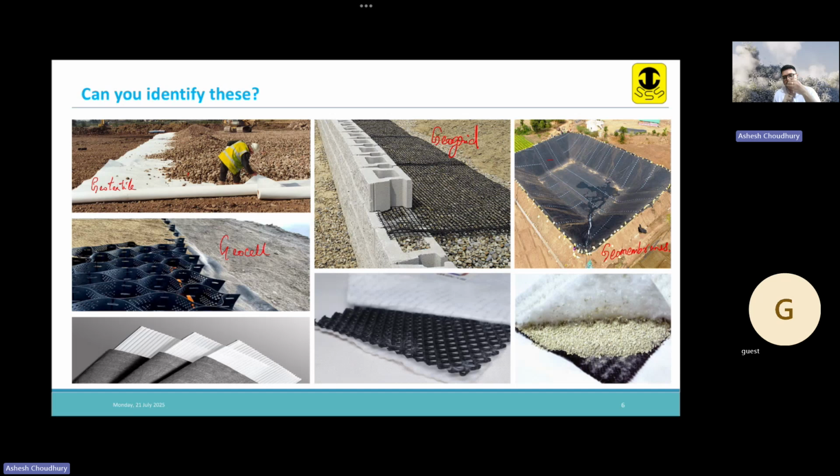Then here we have some corrugated sheet inside, and outside we are covering that with a geotextile. So these are long slender structures, flat slender. We'll see that. So these are called PVDs, prefabricated vertical drains. Okay, prefabricated vertical drains, PVDs.